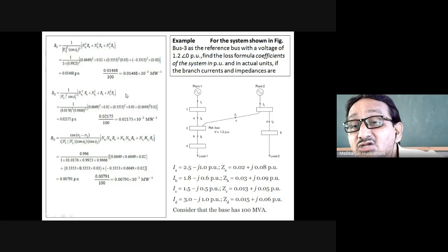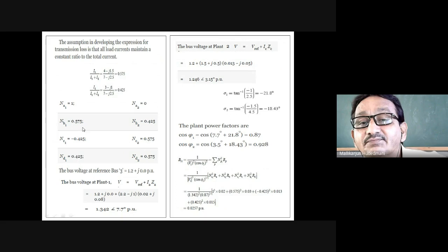Now, direction of current is, it is trying to push the current in this way, but originally marked in this way. Therefore, it is minus 0.425 minus 0.245. When it comes to D, straight 0.425 and to the load. So, minus 0.245 minus 0.425 is the current distribution factor of C section. Plus 0.425 is the current distribution factor of section D. That means